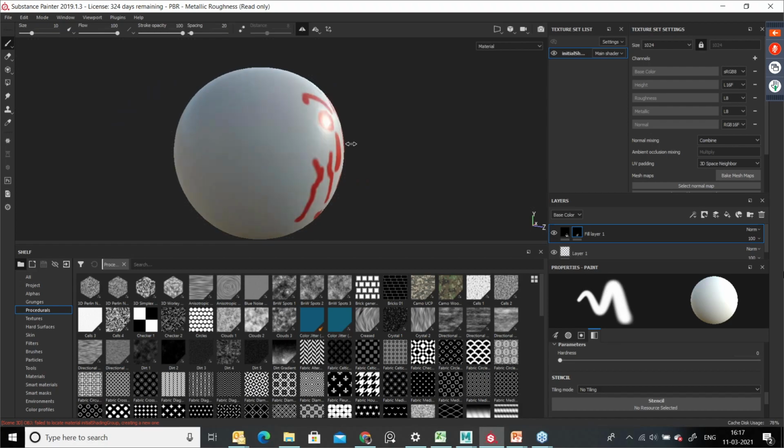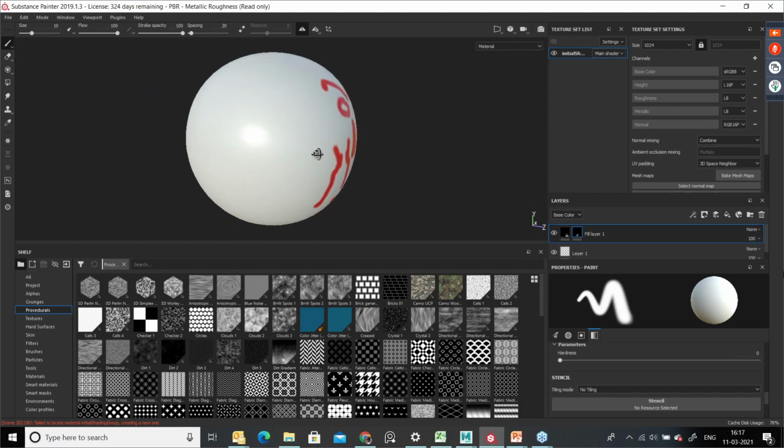The next one, I want to change this direction. So here I want to show something. I have a lazy mouse. There is an option called lazy mouse. Lazy mouse is very famous in ZBrush. In this Substance Painter also, the lazy mouse option is available. But instead of finding the icon, see, this is the icon to activate lazy mouse. You can press D for dog. So you can just get that option over here. Sorry, not symmetry, lazy mouse.